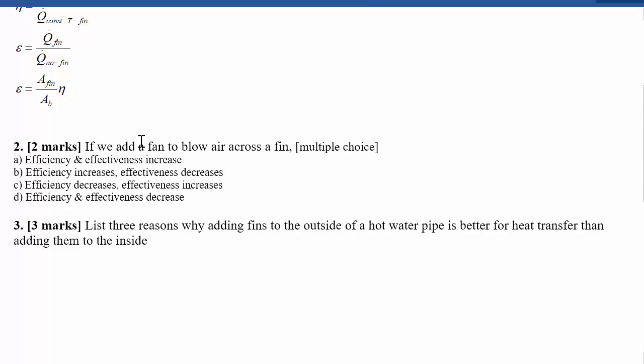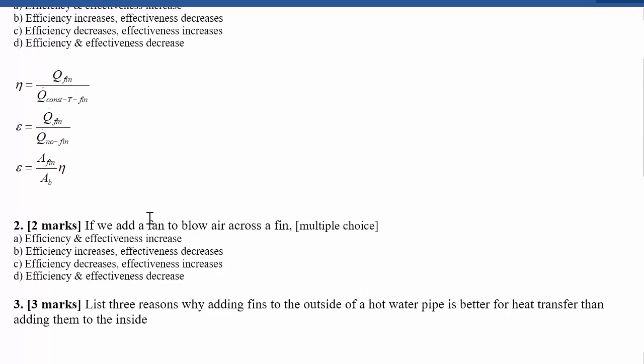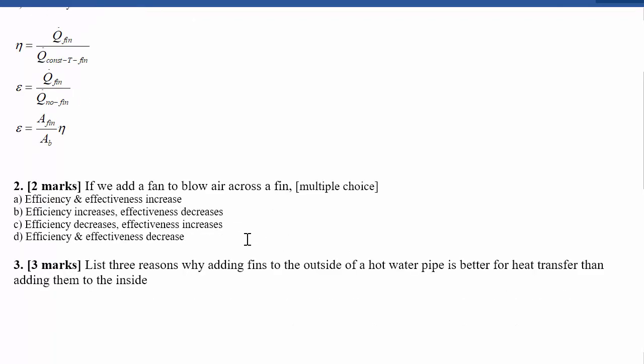If we add a fan to blow air across a fin, then what should happen to the efficiency and the effectiveness? So your first instinct is, oh, efficiency is good, effectiveness is good, fan is good because it's going to increase how much the transfer happens from this fin, and so efficiency and effectiveness maybe will go up again. In fact, they actually both will go down.